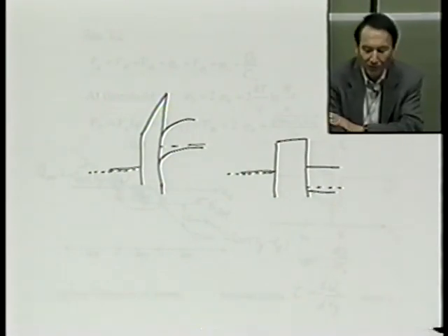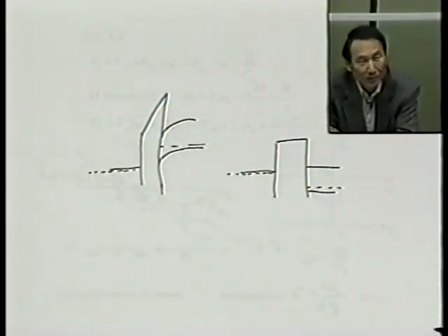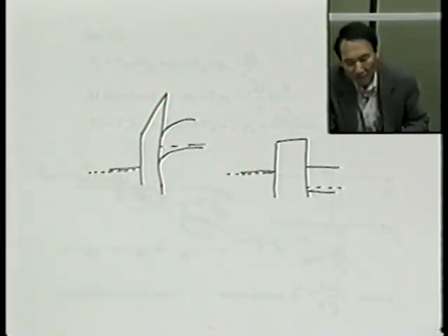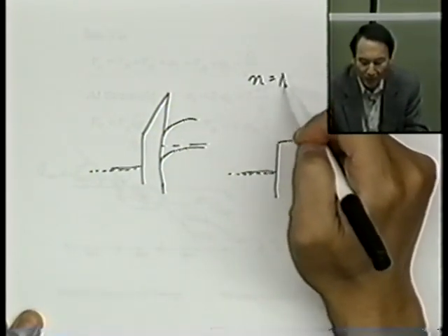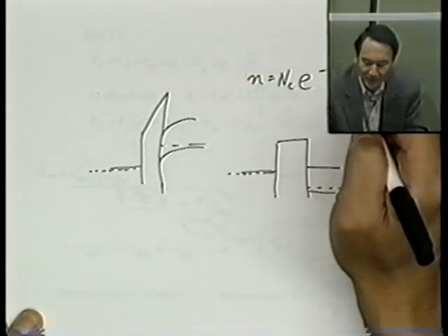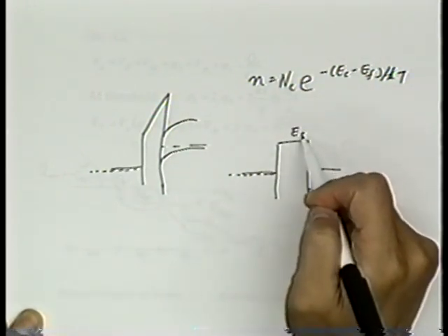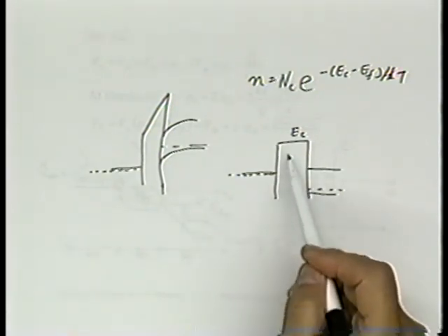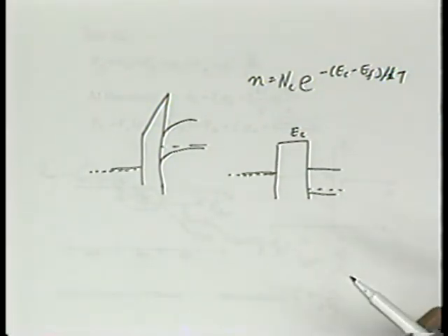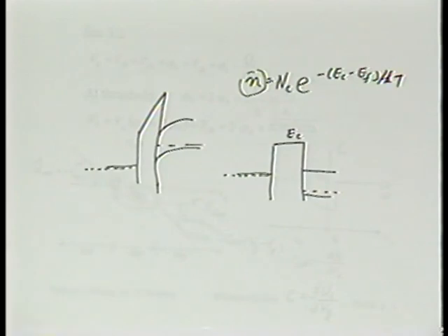Well, it turns out the Fermi level in the oxide does not have any real significance. As a result, we don't pay attention to it. Fermi level has an impact on electronics through this relationship: n equals Nc exponential of minus (Ec minus Ef) over kT. In the oxide, this is the Ec, and Ef is always quite low, below that Ec by several eV. As a result, you can see the electron density in the oxide is supposed to be very small. So that's consistent to that extent.